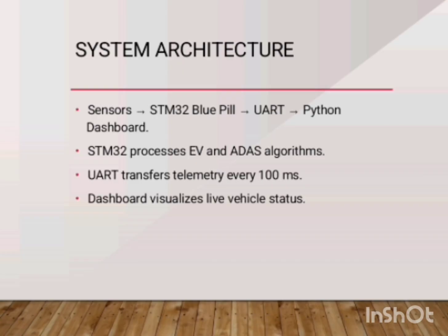The third component is UART communication. After processing the data, STM32 sends the information through UART communication. UART stands for Universal Asynchronous Receiver Transmitter. The communication takes place every 100 milliseconds, ensuring the dashboard receives live updates without delay.